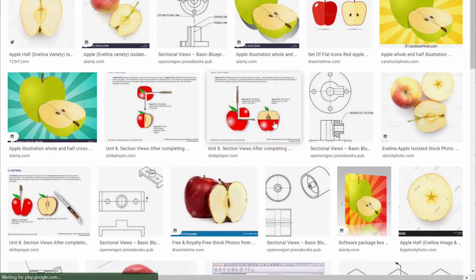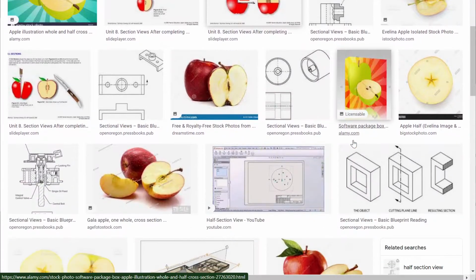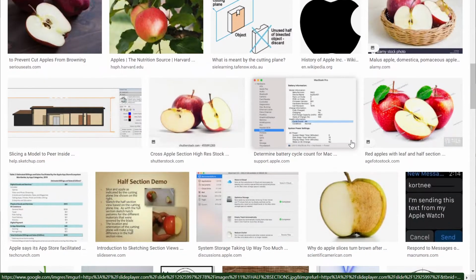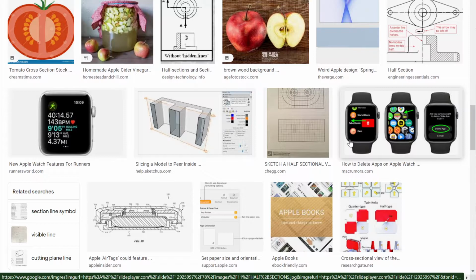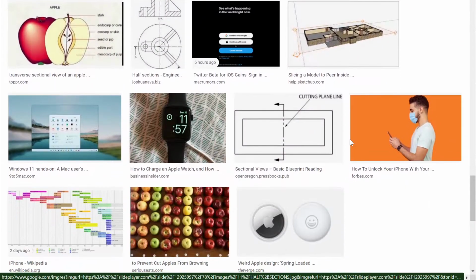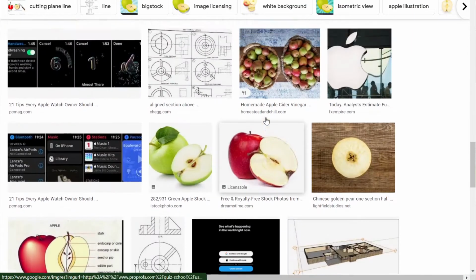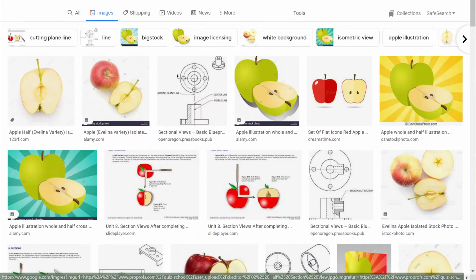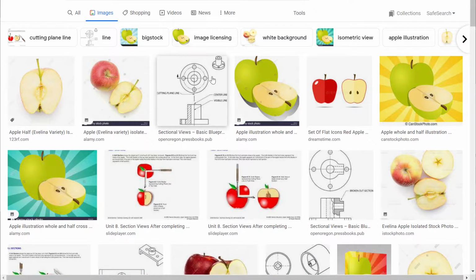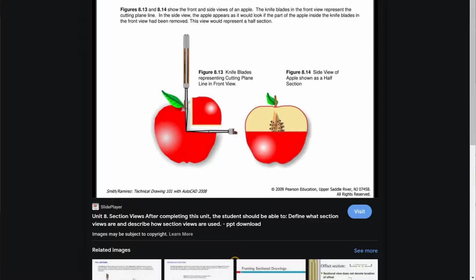That's a half sectional view. That answers the question. Unfortunately, it's not the half that I'd like. The idea is when something has an axis of symmetry, we really want the half sectional view to go through the axis of symmetry. We do again have another example of a half sectional view. So not great, but sometimes demonstrating something that's wrong is good too.